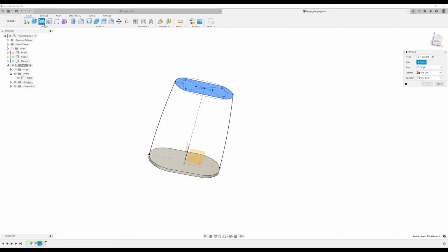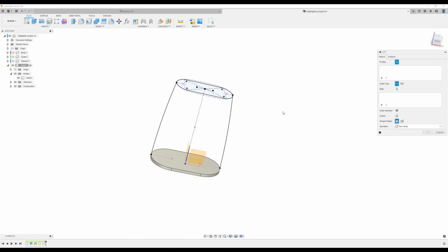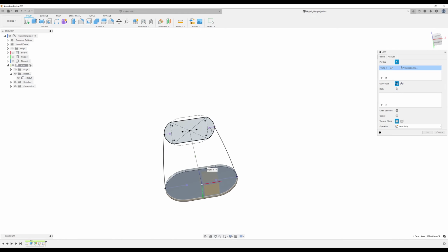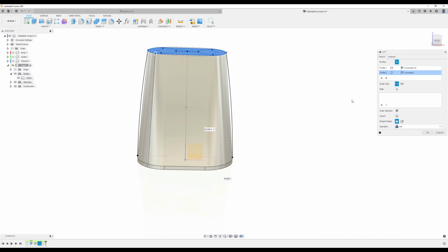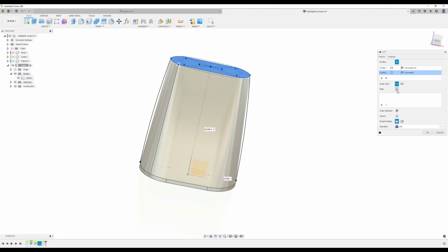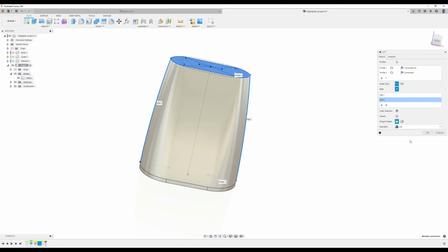Next, we're going to be using the loft tool. Just want to select this bottom face, select the top, and want to select the rails we just created. So click the rails command, select this rail. It's going to be join, tangent edges merge, click OK.